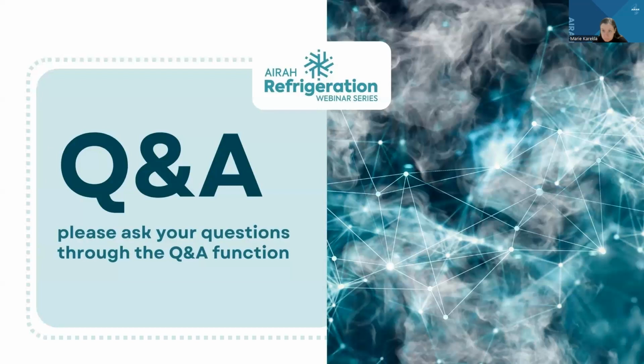Most of the time, freezer rooms don't fall under that category. So I've never come across one that requires fresh air for people working there all the time. Otherwise, you just have to work through, as Andy said earlier, introducing air via outside air and accounting for the additional latent heat loads and sensible loads that come from that. Yeah, as I say, I've not heard of that yet.